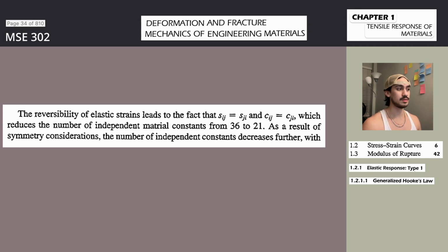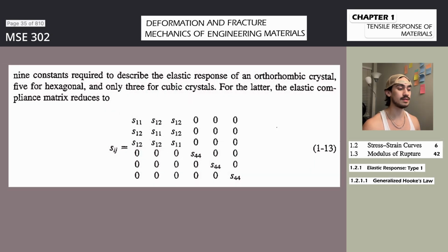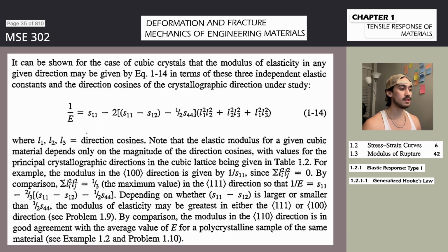However, it is possible for a material to exhibit nonlinear but elastic behavior. For example, very high-strength filamentary particles, often called whiskers, can exhibit elastic strains in excess of 2%. In this range of very large elastic strains, the modulus of elasticity reveals its weak dependence on strain, something that is completely obscured when strains are very small. For example, note that dF divided by dx in Figure 1.2b decreases with increasing distance of particle separation. As such, Hooke's law, Equation 1-7, represents an empirical relationship, albeit a good one at small strains. Consequently, the elastic limit is approximately equal to the proportional limit and may be slightly higher in some cases.